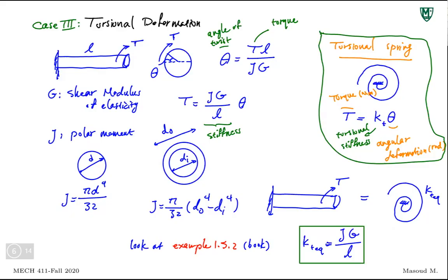In that example, I believe the tank that keeps the fuel for the airplane is attached to the wing, and it can be filled or empty. You will see the natural frequency of the wing changes depending on whether the tank is filled or empty, or how full the tank is, which is an interesting problem because one of the situations you look at is the vibration in the wing.